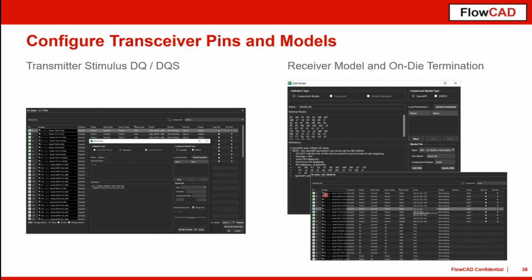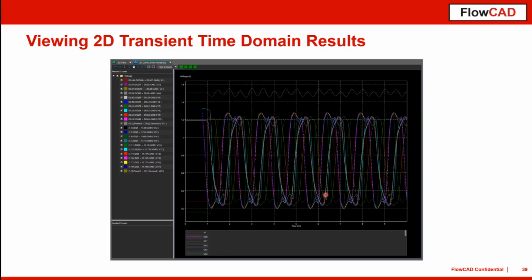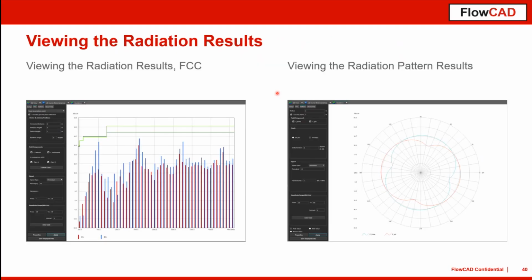Now we also want to show you these results. As you can see here, that is the transient analysis of those selected signals. At the top we have the voltage swinging of our PDN, which is using this non-ideal PDN. That is similar to the EM array result, but from this we can compute the radiation. On the left side, the far field radiation has been computed, and here the green levels show the FCC class A and class B levels.